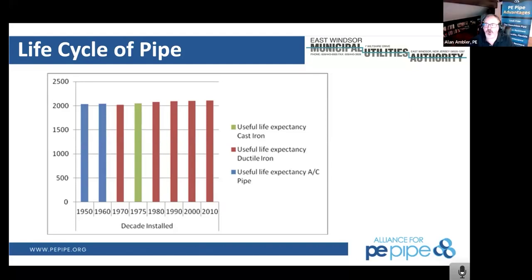Sure. So the Water Research Foundation has studied corrosion in metallic pipes fairly significantly. They have a report that states that in highly aggressive or corrosive soil environments, they can expect to get full pipe wall penetration of new ductile within 5 years. So that's a leak within 5 years, right on that pipe.